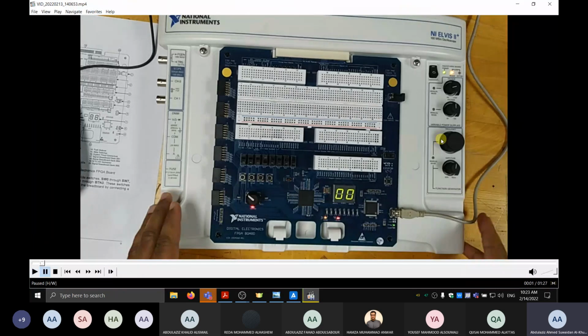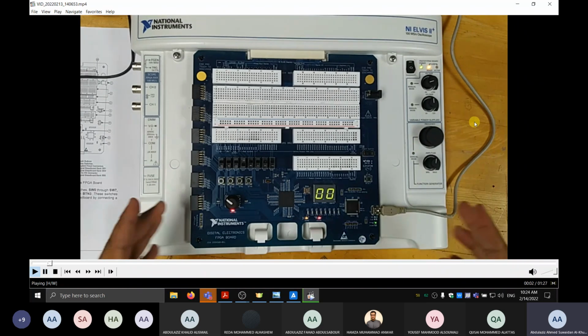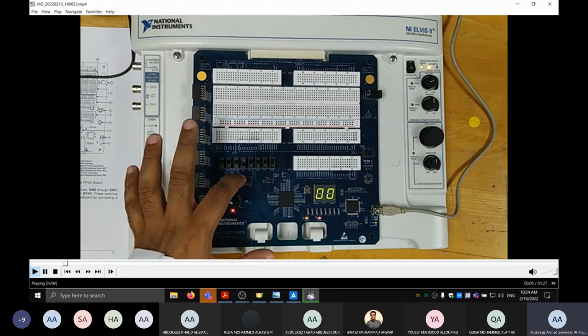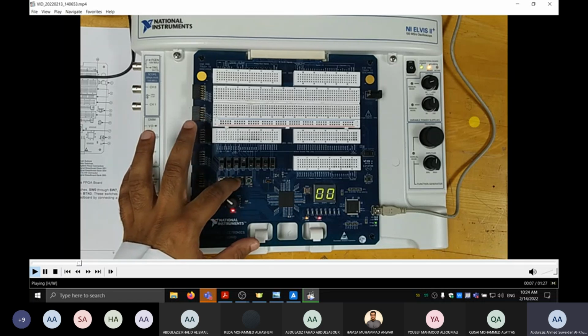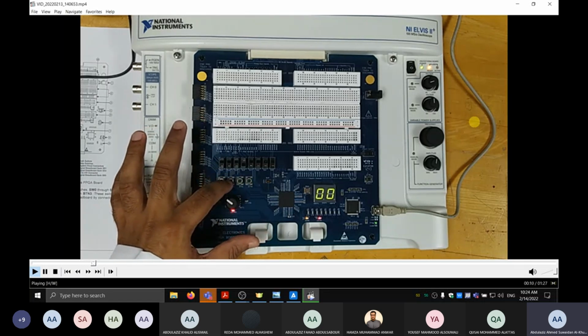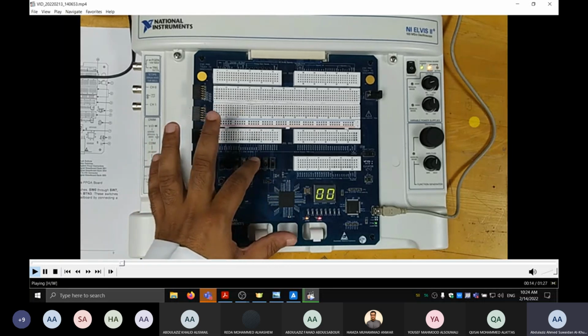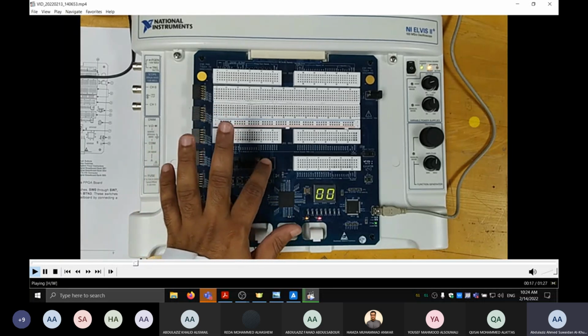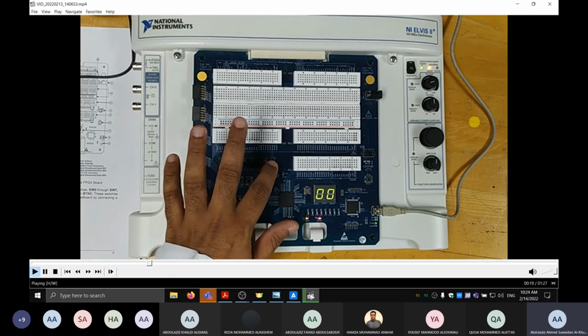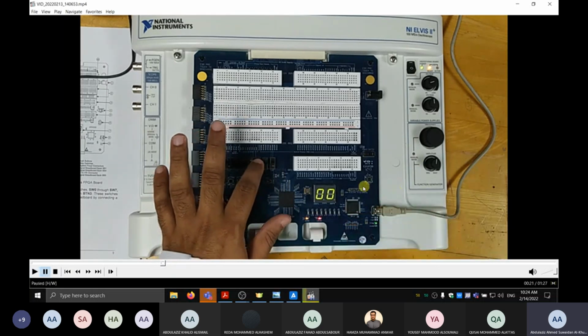Yes, so that's the, you see, I already implemented and I took a video for it. So let's see what's going on. The project here, I already did that. So for the clear, I made it the first button. For the load, I made it the second button. And for the count up, I made it the third one here. And the switches is for the input D, like input switches for the register. So you see, I play with the input, but still nothing happens. Because you see, there is no load signal. Nothing happens. So initially, they both started with 0 initially.